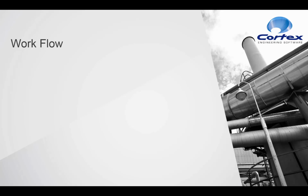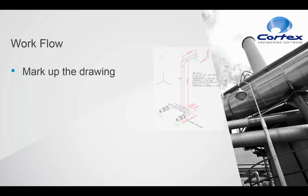The first step is to look at the workflow that we're going to use to get a CESAR 2 analysis out. First step is to mark up the drawing. We take a piping drawing, we make sure that we include things such as the piping code, the pipe sizes, the pipe geometries, fluid conditions, temperatures, pressures, corrosion allowances, materials, and so on.